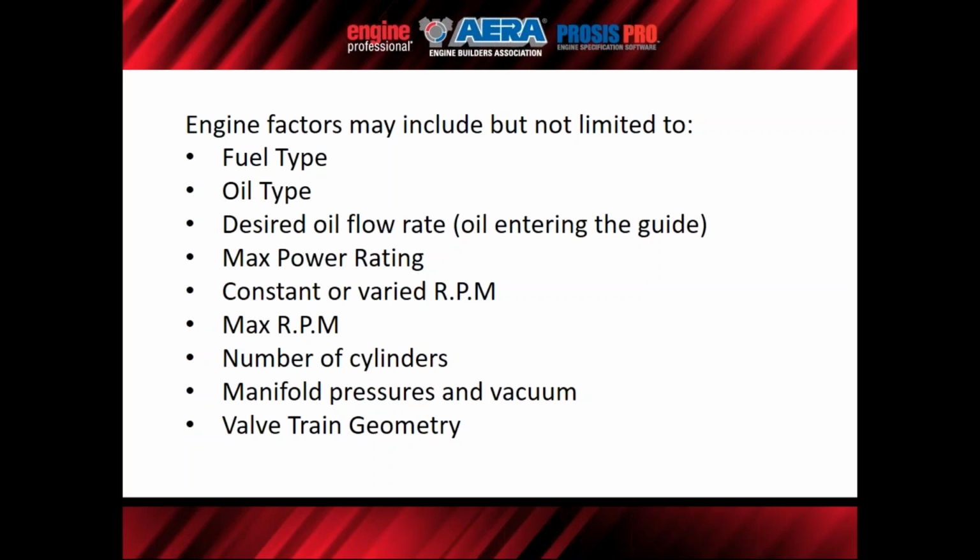If you have something that's an inline, overhead cam, a V engine, those things are all going to impact the amount of oil that is standing around the stem seal. With overhead cam engines, that's as much of an issue as anything. You may have an engine that's got the valve stem seals submerged in oil constantly. So then the flow rate that you're going to allow is really going to be put to a test when you're totally submerged in oil all the time.